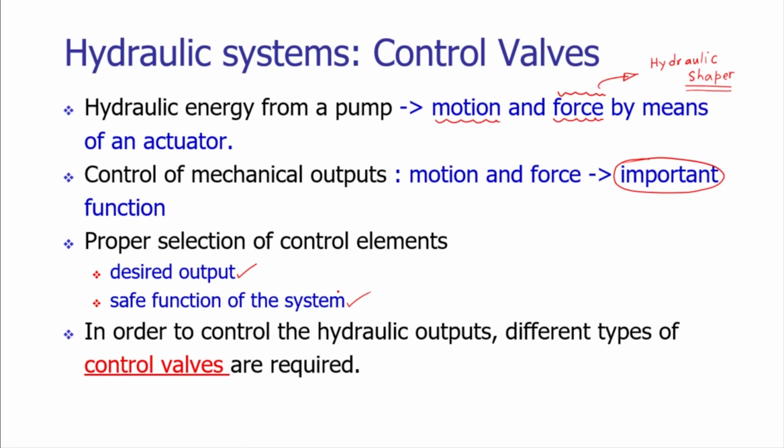The hydraulic valves are needed to control the flow of hydraulic fluid inside the system, to have the required pressure of the hydraulic fluid inside the system, because that fluid pressure itself is generating the required force during the application, and the direction of application.